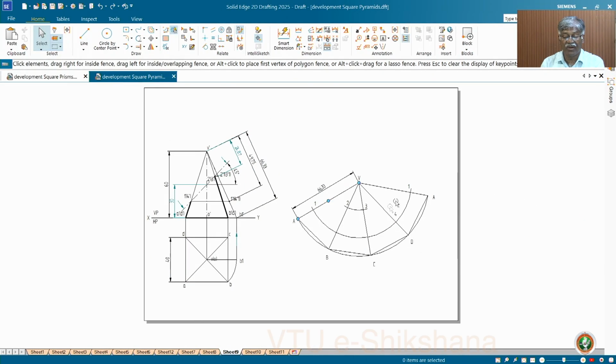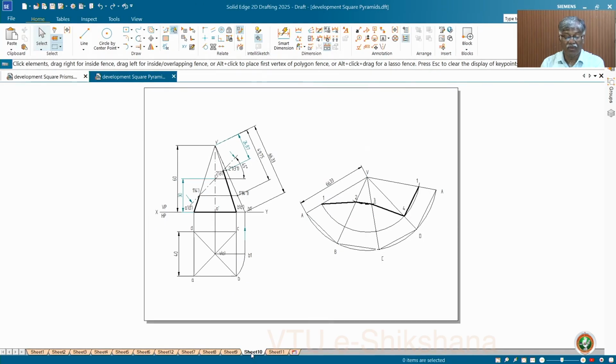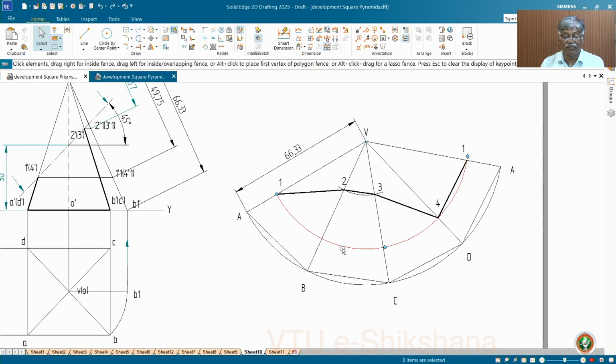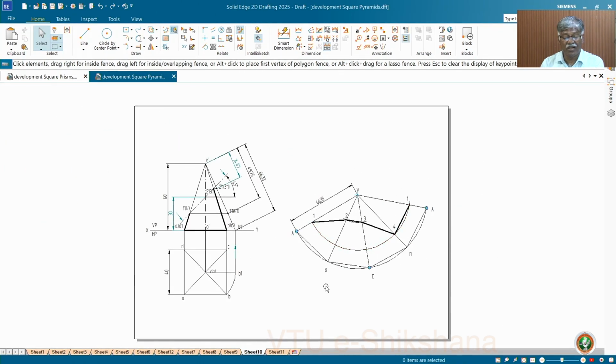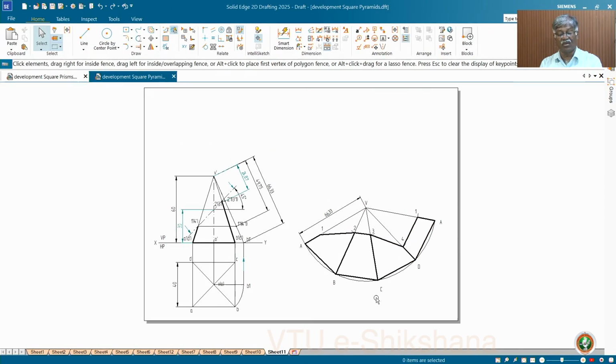You see, I have drawn this. This line covers 3 points, 1, 4, 1, and this. Then you can trim it. After you join, trim it. Okay, you please join and then trim it. No problem. These things you don't want. Trim these two. Otherwise, you independently draw. Then join 1A, 2B, 3C, 4B, 1A, etc. Then also you see that all remaining edges are dark, base edges and part of the slant edges are dark. Okay, so this is how we get the solution.